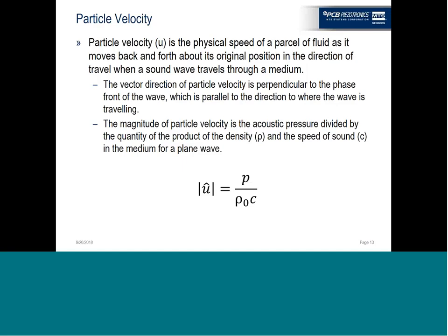And you can ultimately determine the magnitude of your particle velocity knowing that if you're working with a plane wave, and only if you're working with a plane wave, and we'll talk about what a plane wave is in a little bit. So if you have a plane wave and you know your sound pressure and the density and the speed of sound, you can calculate what your particle velocity is. There are other methods in performing the sound intensity measurement using those types of measurements. Particle velocity ultimately falls out of the procedure when you do sound intensity.